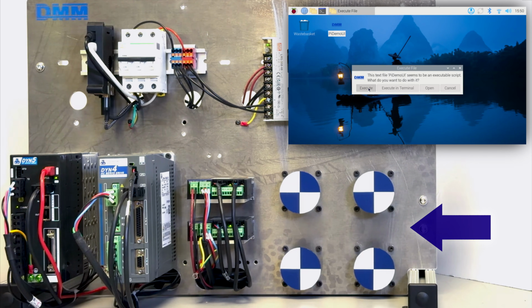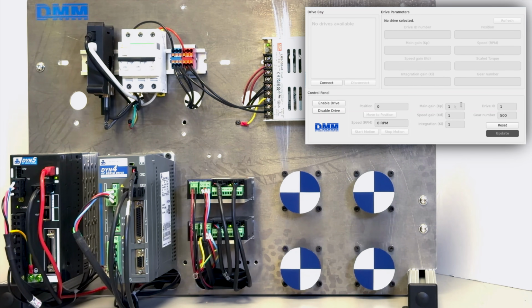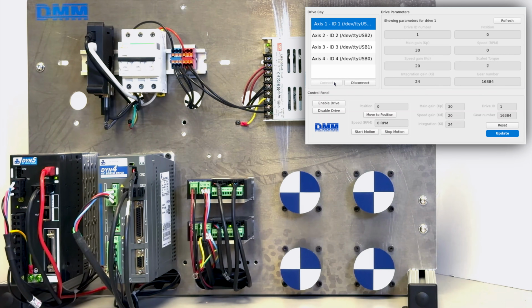motors. Each axis runs in its own communication thread, continuously polling its assigned drive in the background. This allows all drives to stay updated independently without interfering with one another. Axis switching is isolated, and all displayed parameters remain specific to the selected drive.